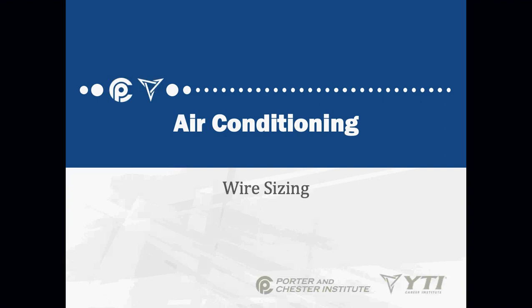And there are fires that happen over this. So if you have an air conditioner sitting outside, and the breaker continuously blows on a hot day, or sometimes when it's starting up, the solution to the breaker blowing is not to upsize the breaker. That's what becomes very important with wire sizing.